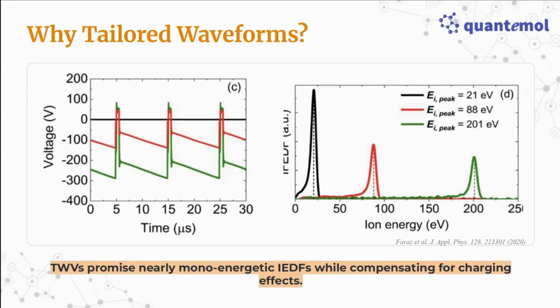And typically, people always talk about DC self-bias. But in the end, it's not actually a DC self-bias. It has transient components, but typically, if you are in the megahertz range, these are small compared to your complete DC self-bias. But that might not be the case if you're at frequencies of hundreds of kilohertz or so. And in these cases, you typically actually have transient behavior of the DC self-bias over this RF period.